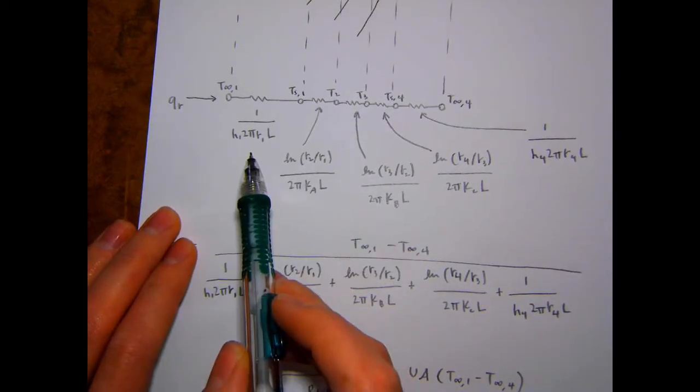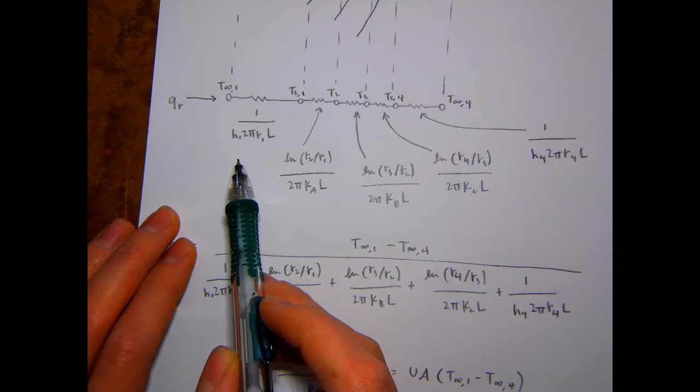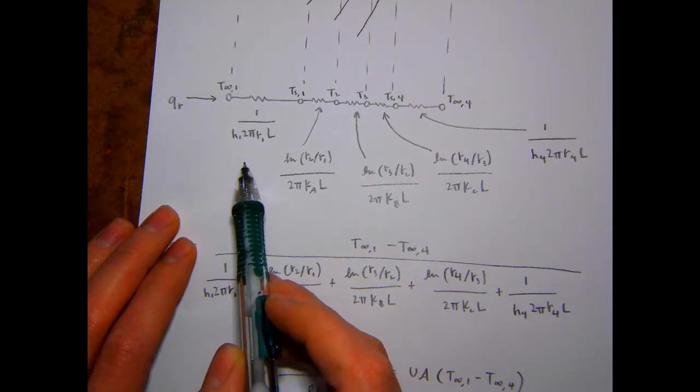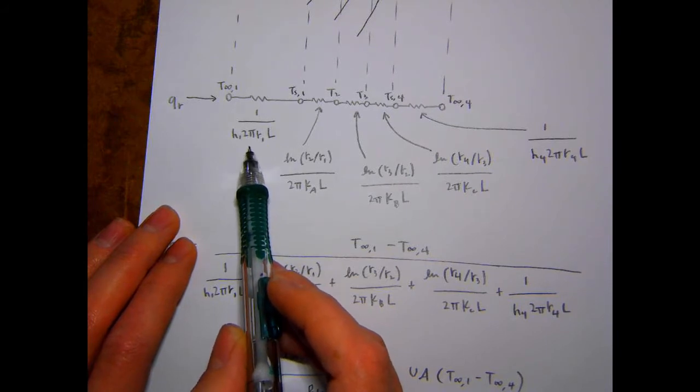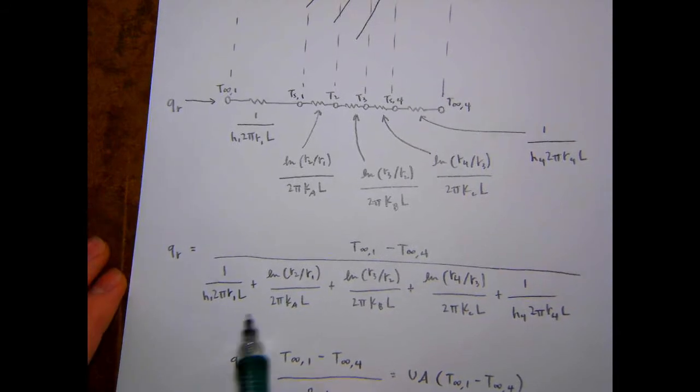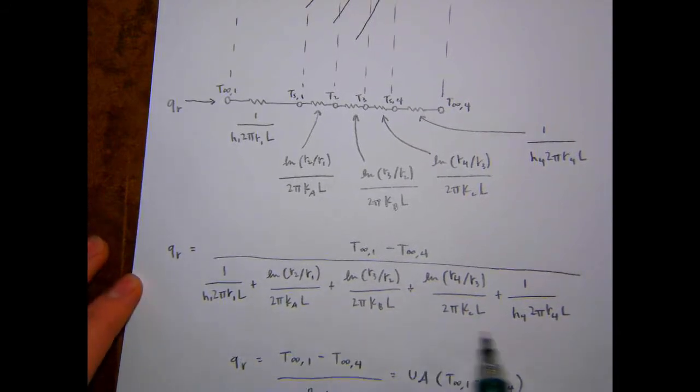So then we can write down this representation of the heat transfer through all these different sections via this resistance concept, and then sum them all up in this total expression for the heat transfer through all of the sections. Like if you say this is just a single walled cylinder with just conduction going through it, this still applies, right?